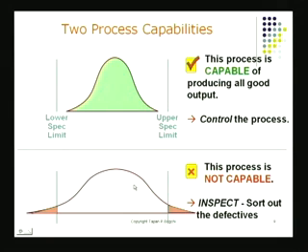Look at this process by contrast. The tails are beyond the tolerance limits, which says if I use this process to supply a marketplace, there will be many occasions when there will be complaints from the customers because some tails of it are beyond the tolerance limits. And this process is therefore not capable. So the green process is capable, but this lower process is not capable.